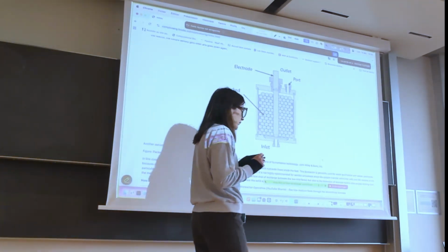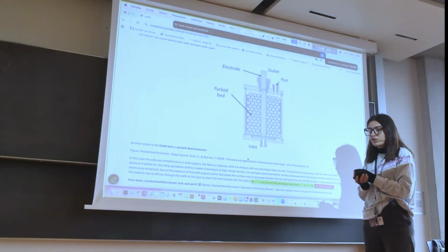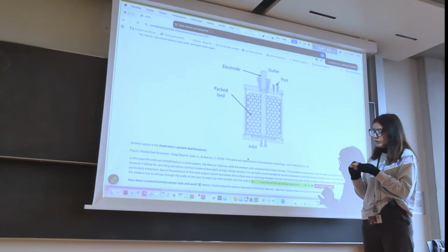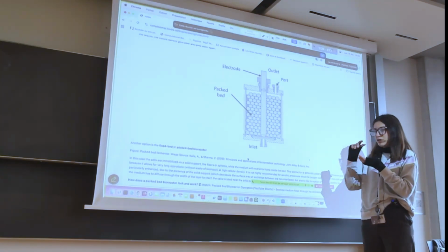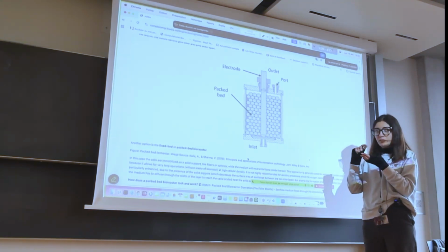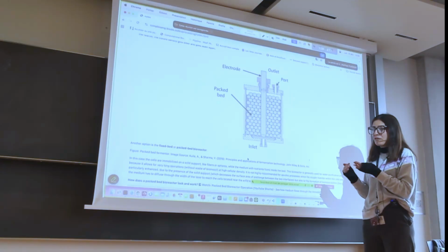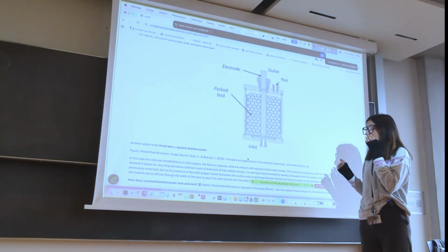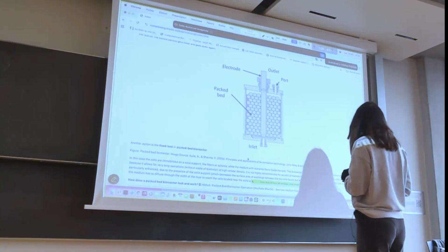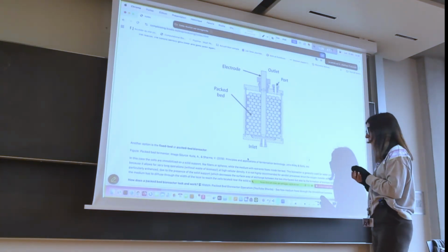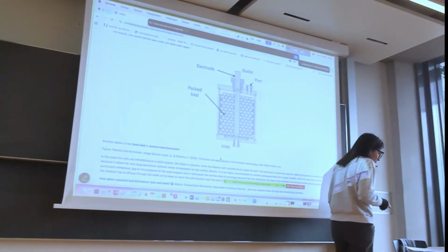But it is not so good for reaction processes that need oxygen, because the presence of the solid structure behind the biomass and the formation of the biofilm on this structure is an obstacle for the diffusion of oxygen from the flow that is flowing through the bed to the cells. So this kind of bioreactor is used mostly for processes where we don't need oxygen.